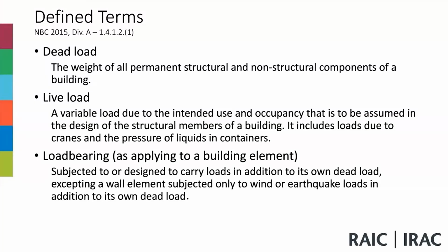Load bearing, as applied to a building element, is an element that is subjected to or designed to carry loads in addition to its own dead load, excepting a wall element subjected only to wind and earthquake loads in addition to its dead load. So when we're looking at an exterior wall element that is subjected to wind and earthquake loads, we don't say it's load bearing.